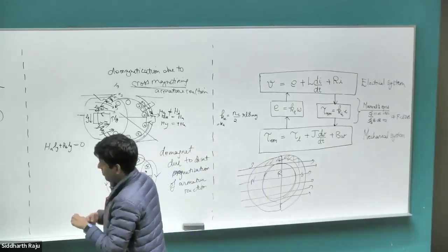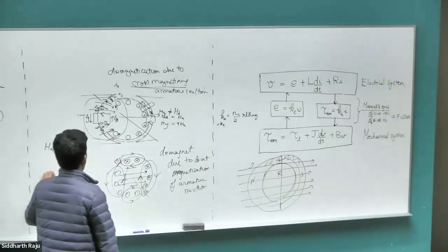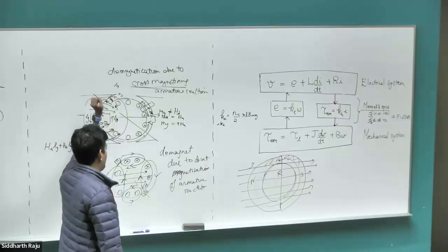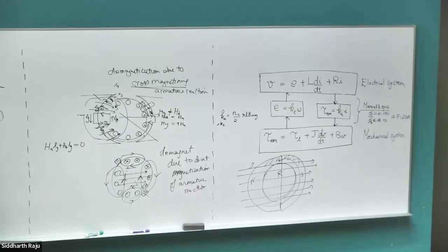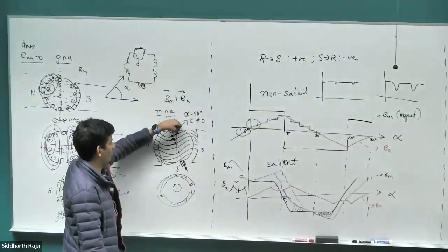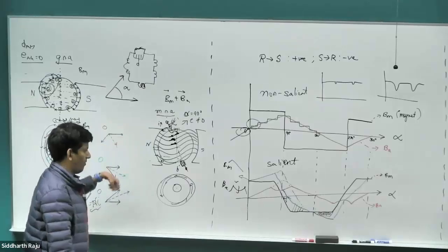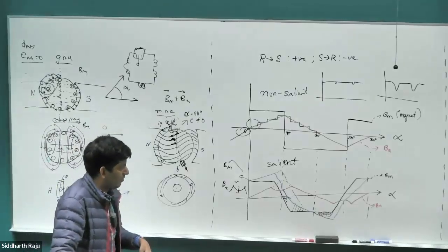Right? So these are the problems that we have with our DC motor. We have demagnetization due to the cross-magnetizing field, demagnetization due to the direct magnetizing field, and then the delay in the commutation because of our armature reaction, which shifted the magnetic neutral axis, which led to some amount of EMF if we had our brushes here, which in turn causes a lot of problems, delay, which causes arcing in our motor. What are all the methods to solve it?